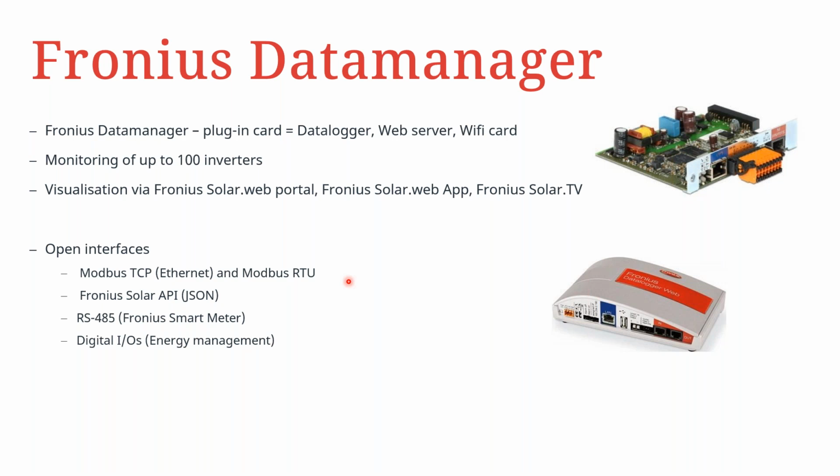Via the same Ethernet port, we can also achieve the Fronius Solar API, using the JSON protocol. Using the RS485 open interface, we can achieve connection to the Fronius Smart Meter. And very importantly, via the digital input-output ports on the data manager, energy management can be achieved.